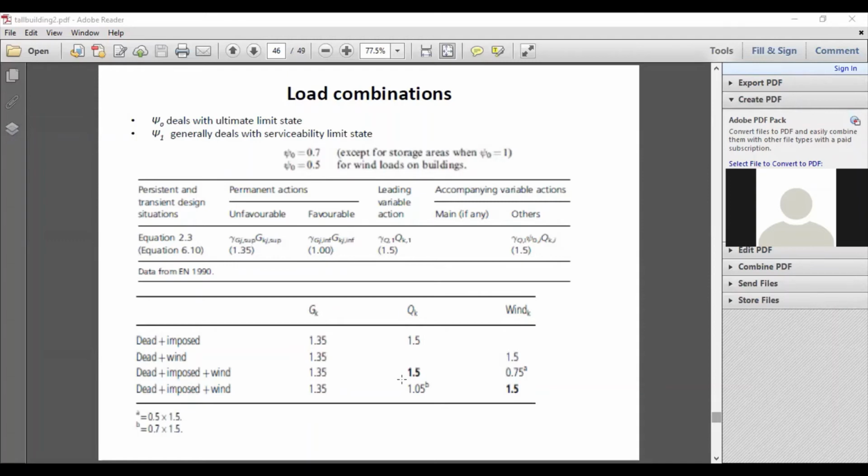So when you assess the values based on probability, you will find that when the building is fully loaded, the chances of a cyclone hitting can be less. So the impact of cyclone we consider as 75% of the maximum value.